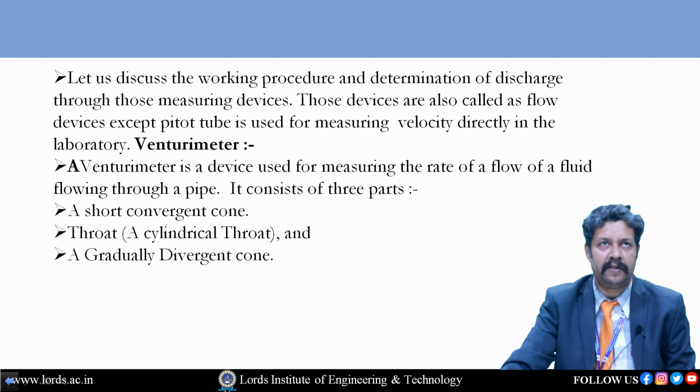So now let us see the function of Venturi meter and parts of the Venturi meter. Normally, a Venturi meter consists of three parts. Number 1, convergent cone. Number 2, cylindrical throat. Number 3, gradually divergent cone. So I will explain the parts of the Venturi meter.